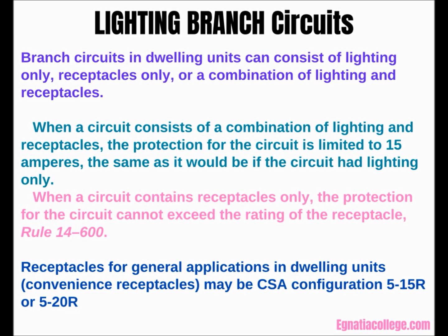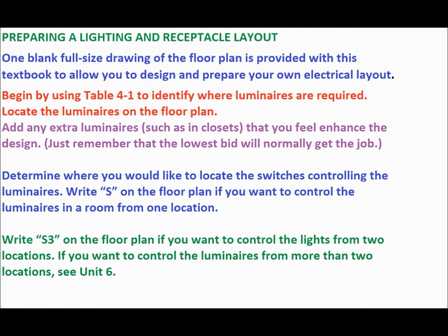Preparing a lighting and receptacle layout. One blank full-size drawing of the floor plan is provided with this textbook to allow you to design and prepare your own electrical layout. Begin by using Table 4.1 to identify where luminaires are required. Locate the luminaires on the floor plan. Add any extra luminaires, such as in closets, that you feel enhance the design. Just remember that the lowest bid will normally get the job.